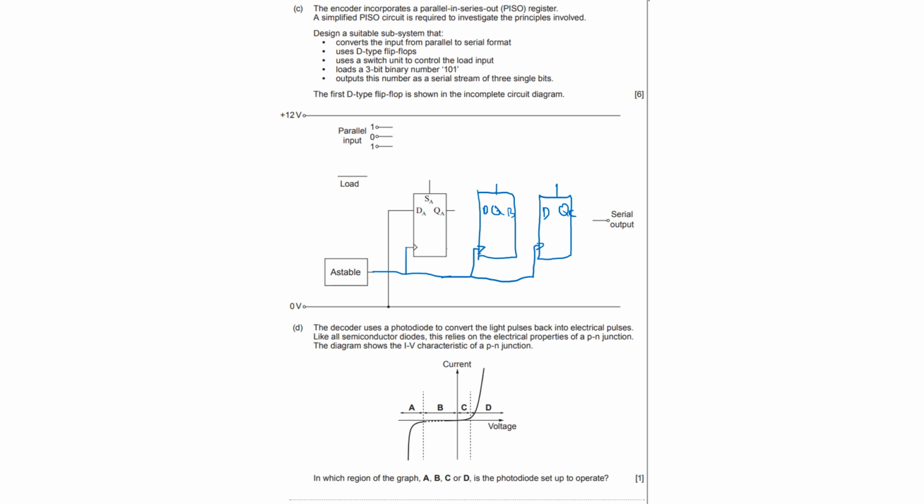It's a shift register, so that goes into there, that goes into there, and that's obviously your output there. And then the parallel input with the load, so we need to move it in, so we need to load it in. You can't just feed them directly in, you need the load. So what logic gate will connect this with this? If you say it in your head, hopefully you can get the idea that you need 3 AND gates there.